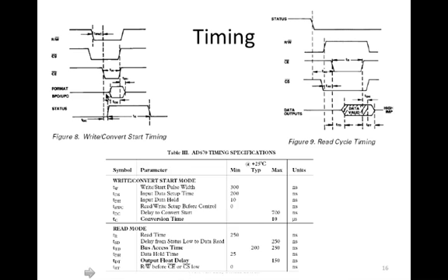What you see is a list of the control signals: R/W, CS, CE, format, status. Well, status is not really a control signal, it's a status signal. And as a part of this diagram, you see these waves representing different values that are possible on these control signals.